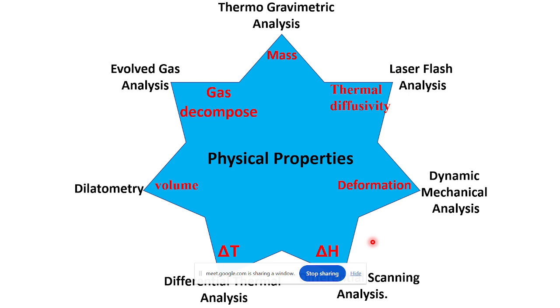Usually we determine Tg from DSC of any polymeric material. You can also determine the Tg from DMA analysis, and you may get a different result from DMA. Thus for the same material you may get Tg at different temperatures from DMA or from DSC. That is basically because of the technique you have applied to determine the Tg. Now in DSC, usually for rubbery material you do the DSC from minus 30 or minus 25 degree centigrade up to 300 or 400 or maybe 800 degree centigrade.